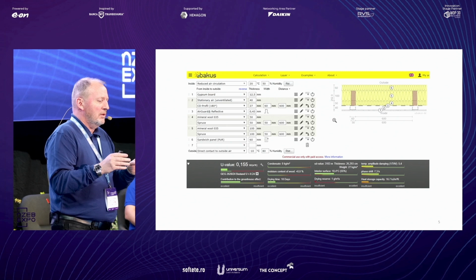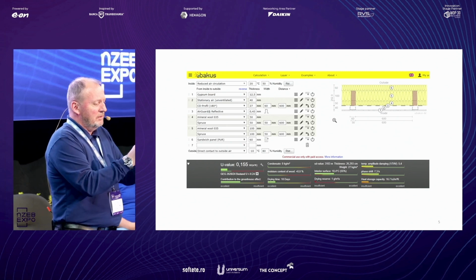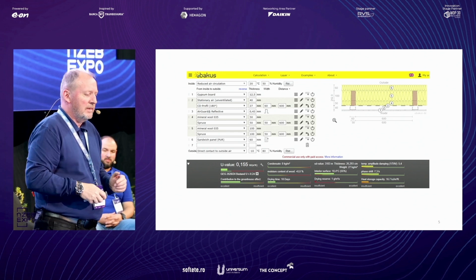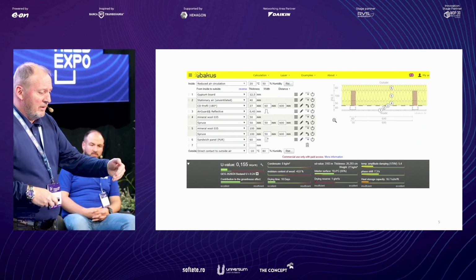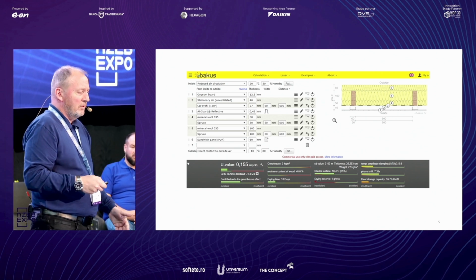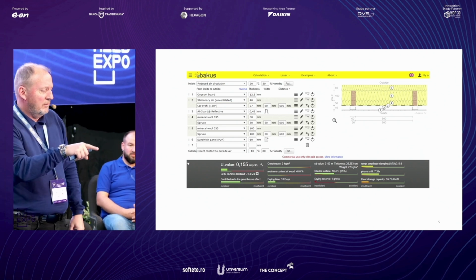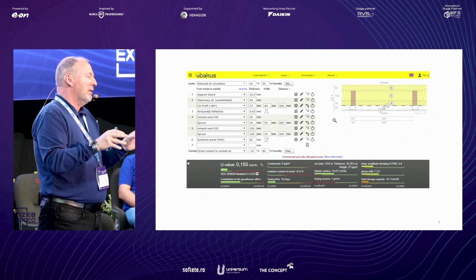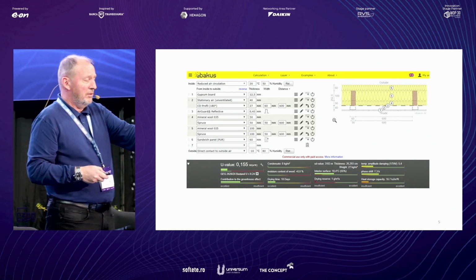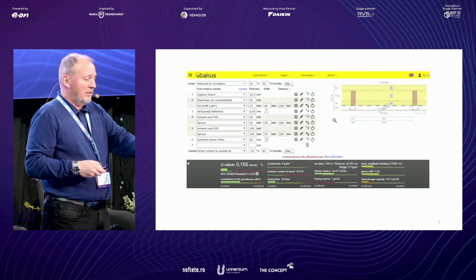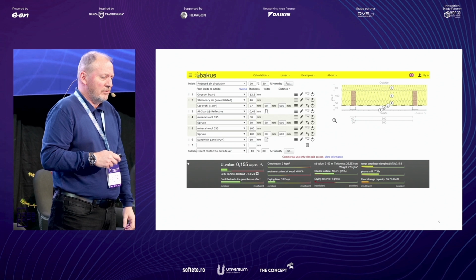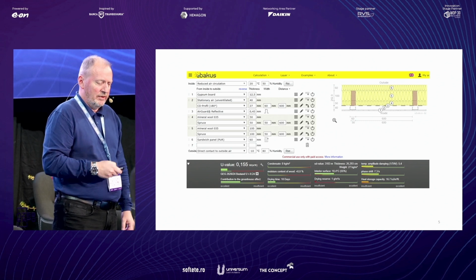What we're actually showing you is what you design and what you build are not necessarily exactly the same thing. So this particular case, this build-up, I understand is reasonably common, this part of the world. And you'll notice that the system, number 3 there, has a very good air and vapor control layer, which is very nice, actually. You can see your U values are good. The air and vapor control layer, reducing condensation, not to a satisfactory level. 0 is always satisfactory, obviously.